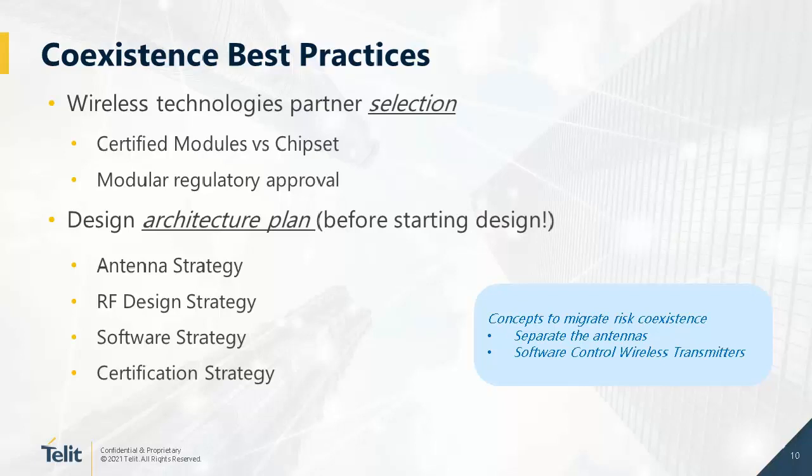And then you need to make sure that it has modular regulatory approval. What modular approval means is that you can reuse the test results, you can reuse all the work that the module provider already did with the regulatory bodies. That really streamlines the process for your device, whether you're using coexistence or not.